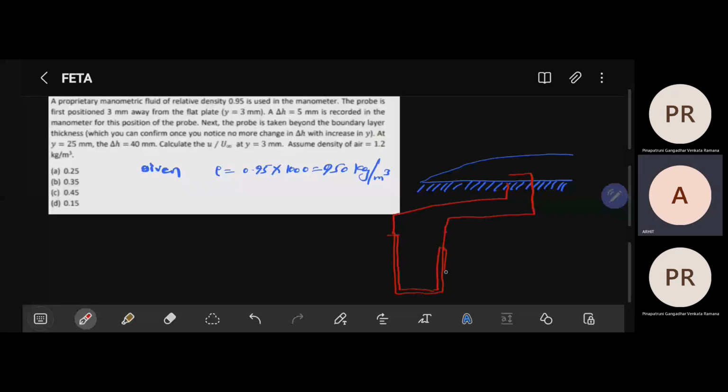Yes, sir, I got it. Actually, I did the same arrangement, but I was thinking only that. Now the difference is that as you connected to the two legs of the manometer, your stagnation pressure, I mean the limb on the right side, whatever the stagnation port you connected, has more pressure on the top, so that's why it is lower.